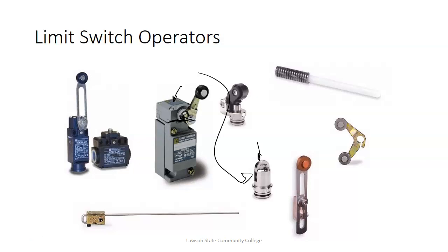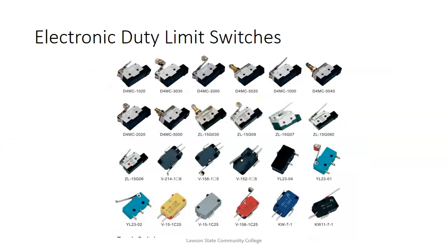These guys, like I said, are a lot cheaper compared to solid state or electronic sensors. As long as you maintain them and don't expose them to something they're not supposed to be exposed to, they last a long time. And of course, their big advantage is they're cheap. So if they can use one of these instead of a photoelectric sensor, which you have to keep clean, then they're going to use one of these. These work in harsh environments if you keep them all sealed up. These are the ones that we have on our manufacturing lines.